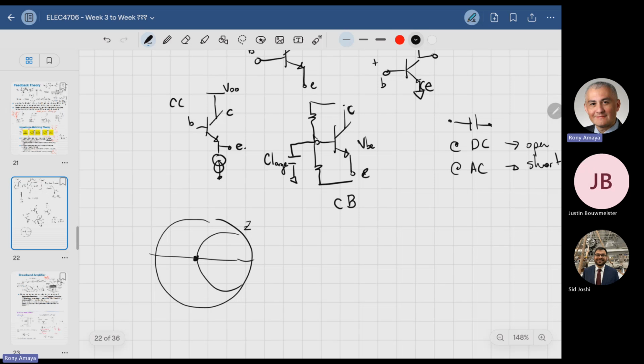So perfect matching typically is achieved by trying to get as close to the center of the Smith chart as we possibly can. Right? But we don't normally specify a single point. We actually specify an area. And that area, which is basically a circle, can define the return loss, let's say 10 dB, or the gamma 0.316, or the VSWR of 2 to 1.